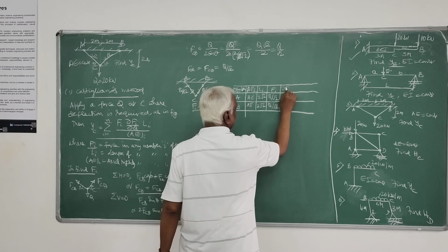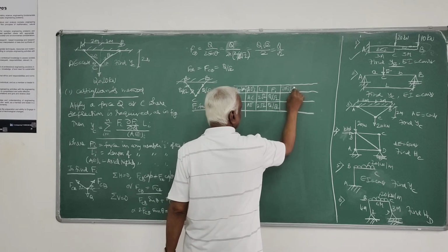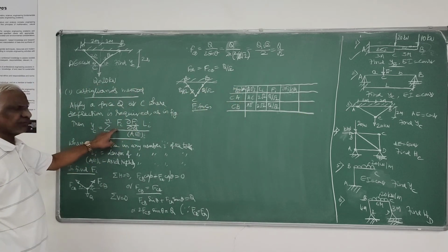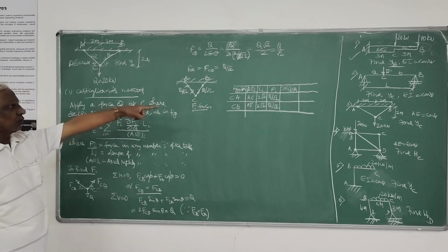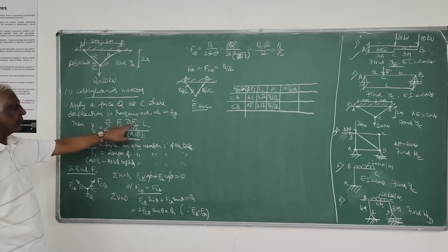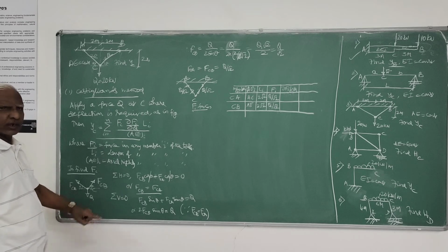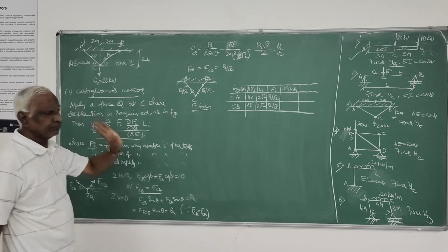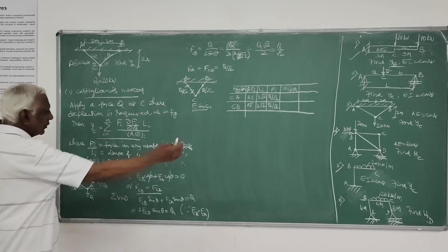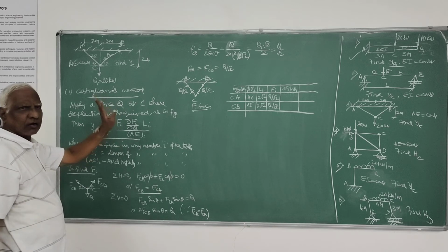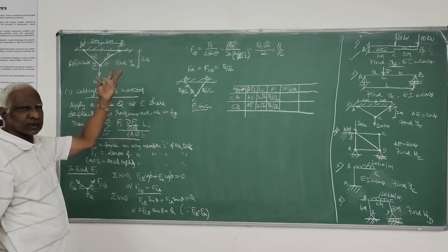Then find delta F5 by delta Q, because we need to have found out F5 in all the members. I is equal to 1, 2, because there are two members. I have determined this F5. Delta F5 by delta Q, I determined this Li, AEI, already I have tabulated. All these values I will substitute, adding from I is equal to 1 to as many members as there are in the total structure.